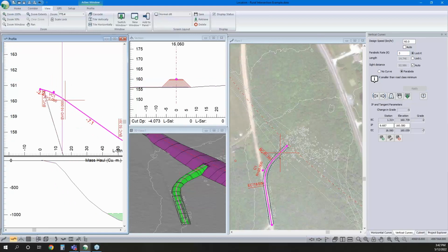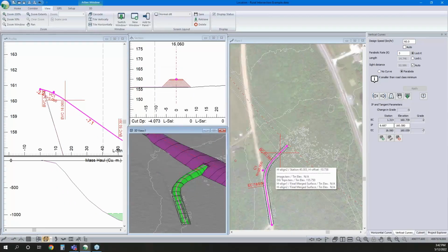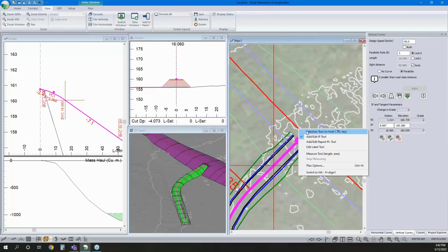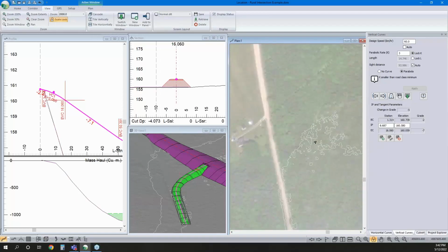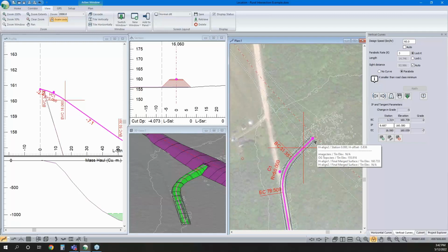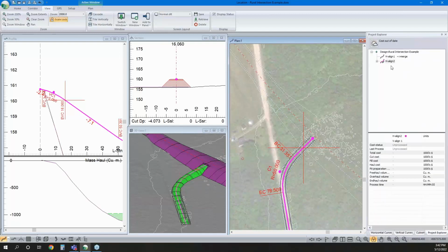And we've got kind of our elevation figured out, our grades, but of course one of the big things that we'll likely want with a T intersection is to get that flare to transition onto the other alignment. So for that I'll use reference features. So this has been in the software pre-version 10, but being able to merge surfaces certainly complements it, to do things like what we're doing here.